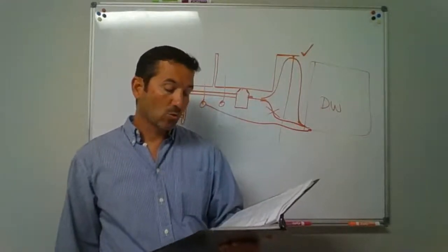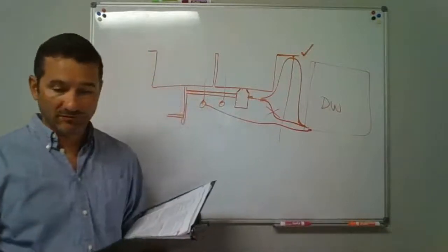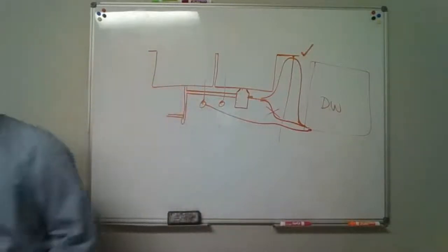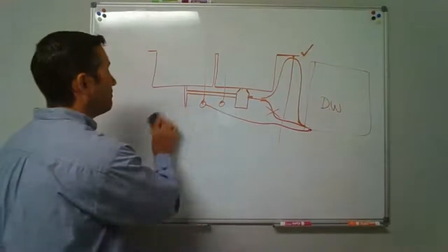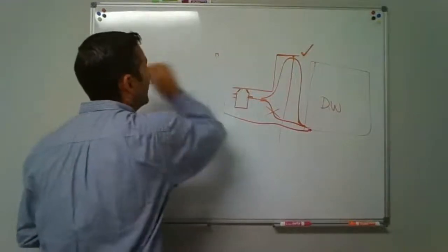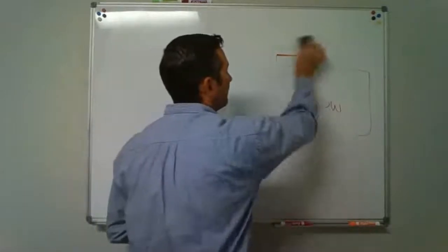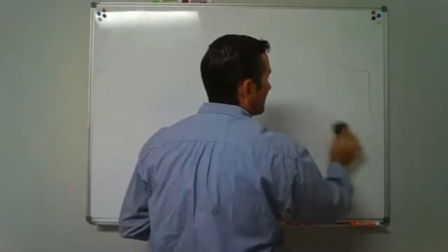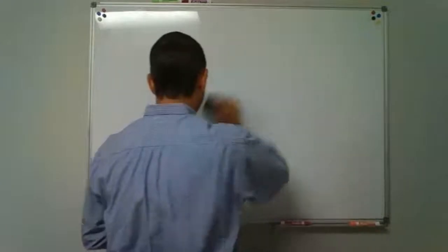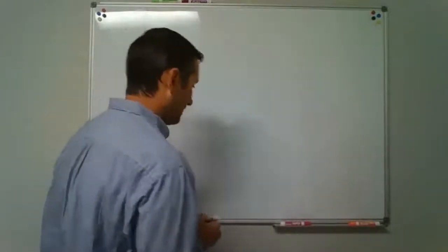So the indirect waste pipe itself must be trapped, and it gives you two parts. It gives you a horizontal distance, the maximum it can be, and then a total distance on that pipe that it can be.